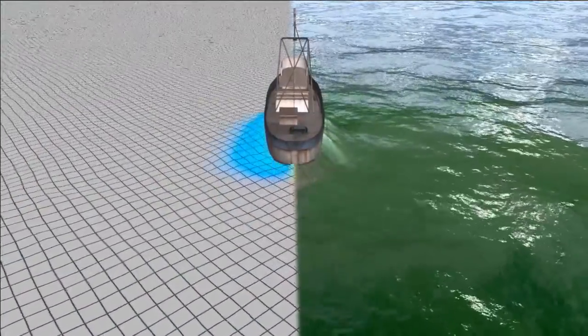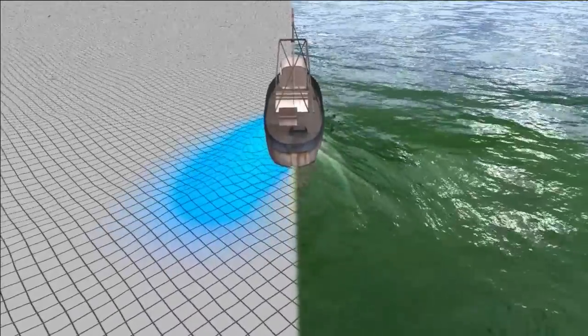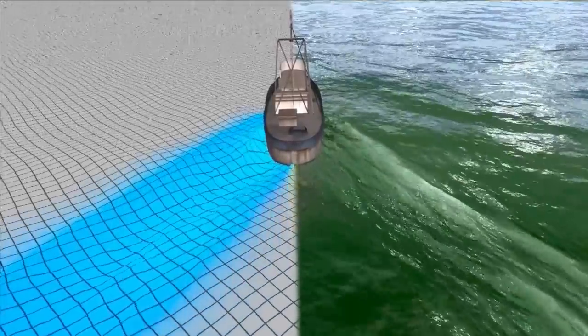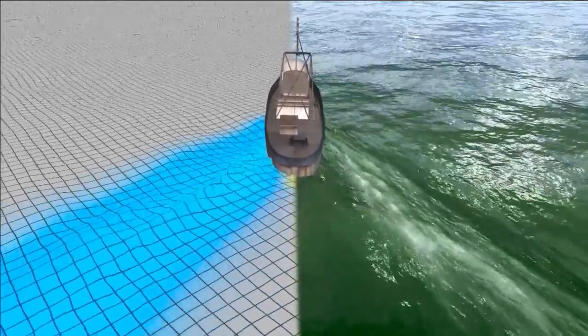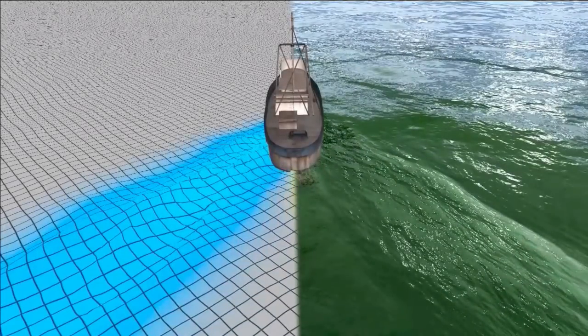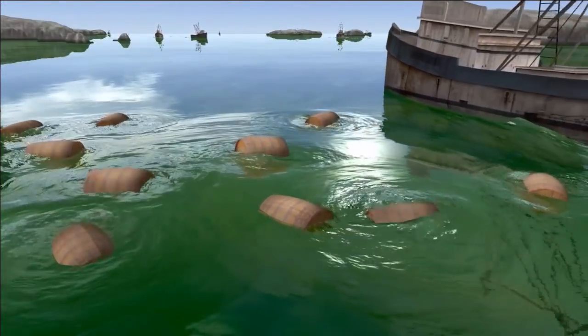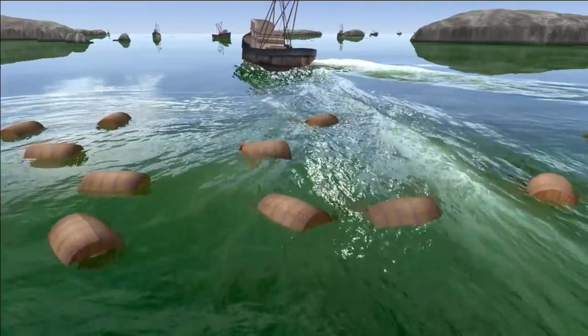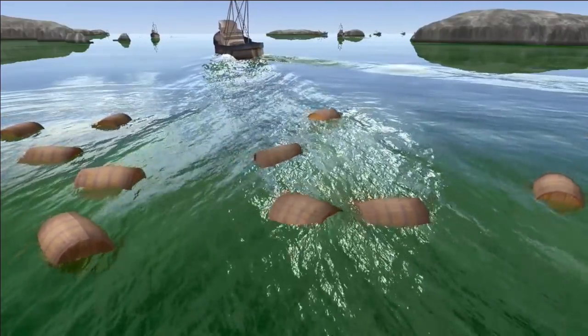To illustrate how the solver works in practice, here on the left, you can see the amplitude data. This is this blue function on the grid. Compared to the right, you can see that the amplitude values are really a smooth function compared to the wave heights on the right. So we get much better CFL and Nyquist limits on the amplitude function. This is the reason why we get away with this relatively coarse grid and still get all the details. We also provide some basic object versus fluid coupling. Solids and water exchange energy via buoyancy and the amplitude simulation grid. Again, details are in the paper.